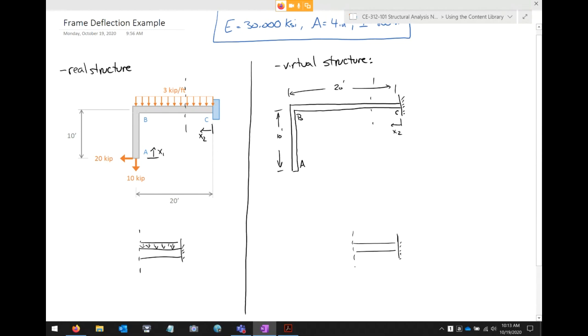I propose that if you define your big moment like this, as long as you define your little moment the same way, the sign convention washes out. Because ultimately, the only convention you care about at the very end of the problem is the assumed direction of deflection. So let's go back to this problem.